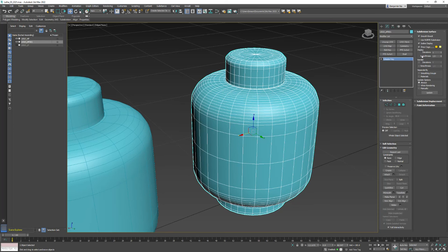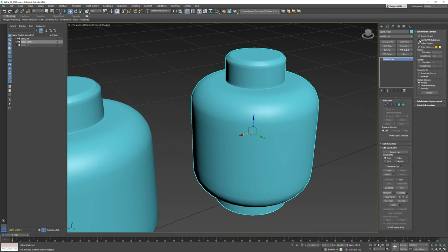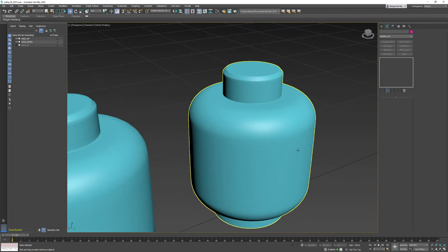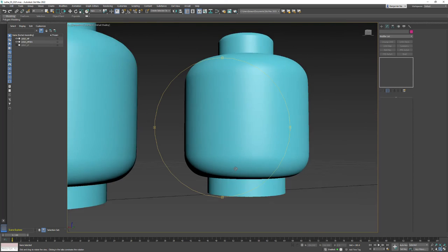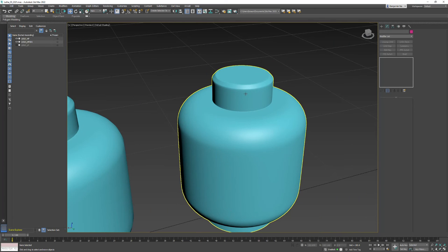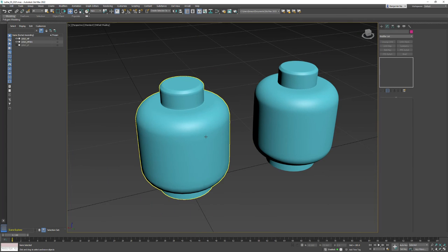So you want to be careful that you're not baking your meshes down with NURMS turned on, because you may not want that. Now, if you really want to get it to be extra smooth, you can actually turn it on, and it'll remember that. So then it's even smoother. But that may not be a clean way to do it. That may not be what you're looking for, but the general idea here is you're going to end up with two different versions of your model.